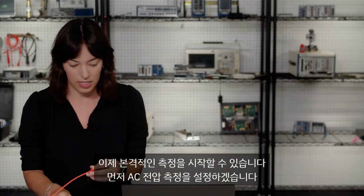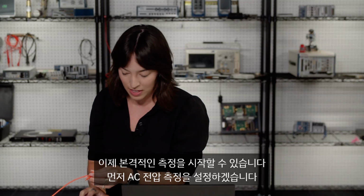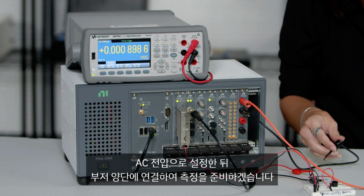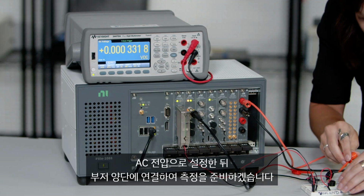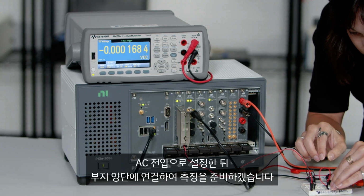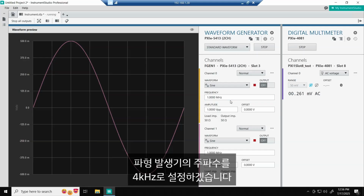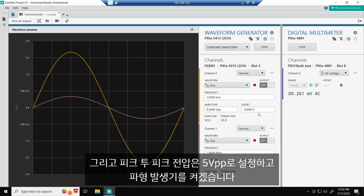I'm going to go ahead and set this up for our DC voltage first, or AC voltage, sorry. We'll set that, and then let me set these connections really quick so that we can measure across our buzzer. Then on our waveform generator, we'll set this to 4 kilohertz, and then 5 volts peak to peak. So we can go ahead and turn our waveform generator on.